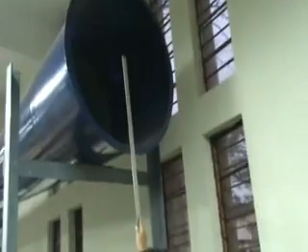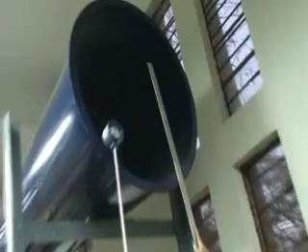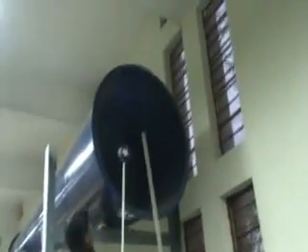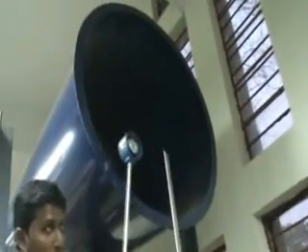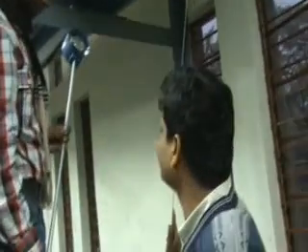Now if you come and do the quantity survey here using the anemometer, then we can find out what is the velocity of air which is flowing through the duct. And if I take the dimension of this duct at the outlet, the area, and multiply that, we will get the quantity Q.